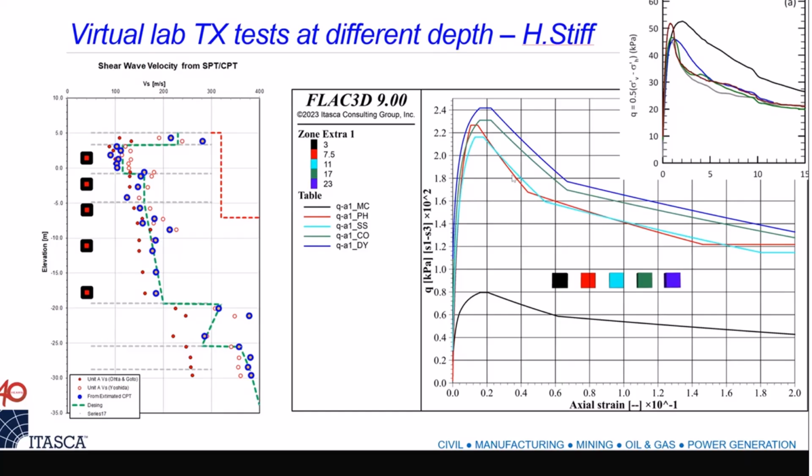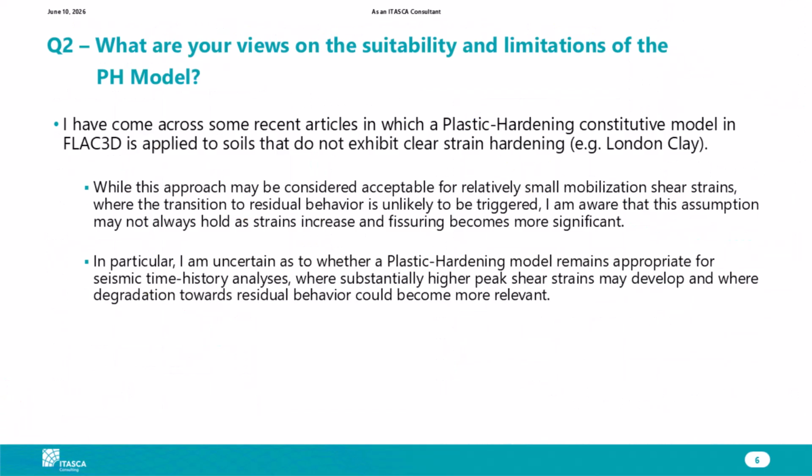And again, even this lab activity is a tool that is still related to shear wave velocity to determine all the stiffness, and then the nonlinear strength envelope, the typical power law, in which we have the A and B to determine the shear strength of the material. Going back to the question, we can accommodate large strain softening in the plastic hardening. This module is not commercially available right now, it is something that I have for my own consulting. At some point, maybe we will develop it and make it publicly available. Although I have to specify that this is for static.